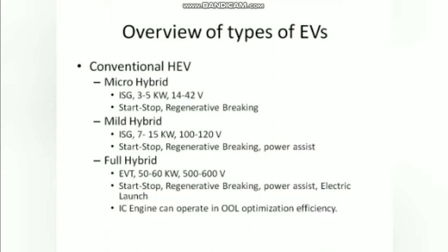So the classification of all types of electric vehicles in terms of propulsion devices, energy carriers and energy sources is elaborated here. In terms of propulsion system, a hybrid electric vehicle primarily uses an engine and electric motor, while a pure electric vehicle uses solely electric motors for propulsion. On the other hand, if we classify the EVs on the basis of energy carriers, hybrid vehicles use either liquid fuel or electricity as energy carriers, while a pure electric vehicle uses either battery or hydrogen as energy carriers.